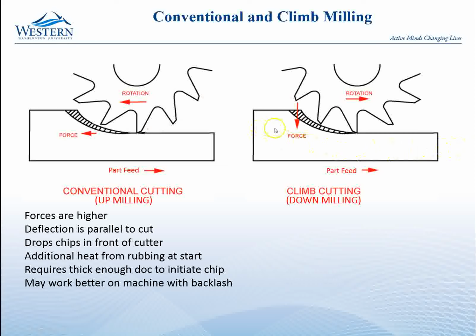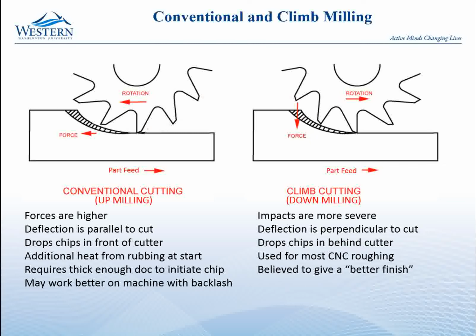But this time, as the part feeds past and this next tooth comes in to cut, it's hitting right here on this surface. So it's not a gradual entry into the material like we had in the last one. It is a sudden entry. So it whack, it hits, and as soon as it hits it, it's in full cut, and it's taking this big chip, and the forces get smaller, smaller, smaller, and then it throws them. So the biggest force is right here where it begins to cut. And so it puts this big force onto the part right here at the beginning, and the force is perpendicular to the axis of motion.